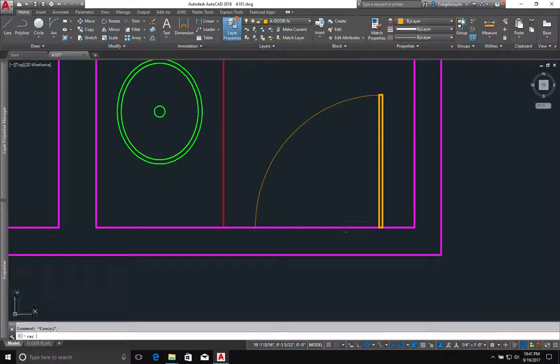And now I'm going to use my rectangle command, and I will draw in some jambs. And you can see I'm just hovering my mouse to get my object tracking points established, and I don't left click, and I'm entering my distance as I go.